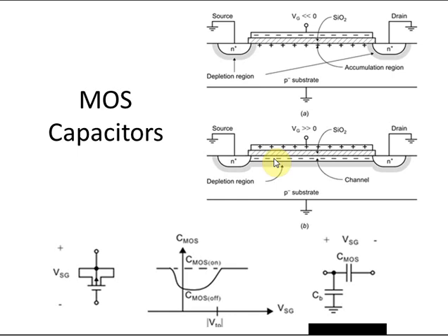The way this is usually implemented in practice, a MOS capacitor used as a varactor in an analog circuit would actually be using a PMOS device, not the NMOS device shown here. Why? Because a PMOS device provides an independent connection to the body terminal. And then by shorting together the source, the drain, and the body, they together form one plate of the capacitor, if you like. The other plate is formed by the gate. So you've now got a two-terminal device, effectively: gate and source-drain-body. And the capacitance between those two terminals depends, as we talked about, upon the voltage between them.